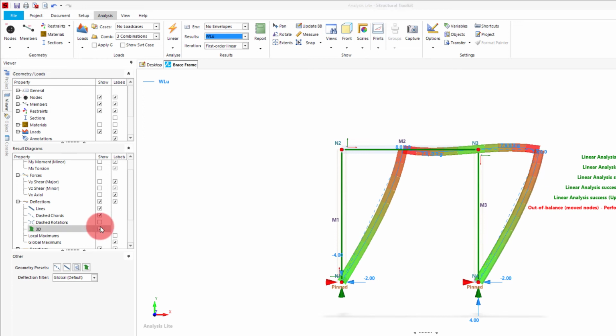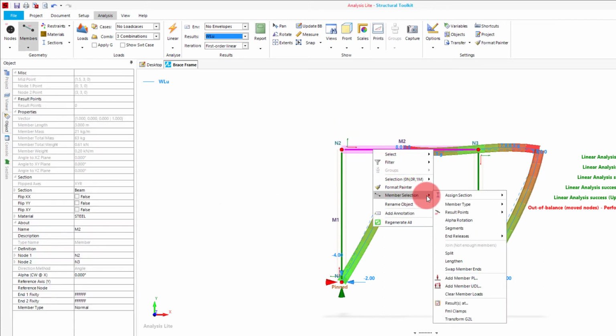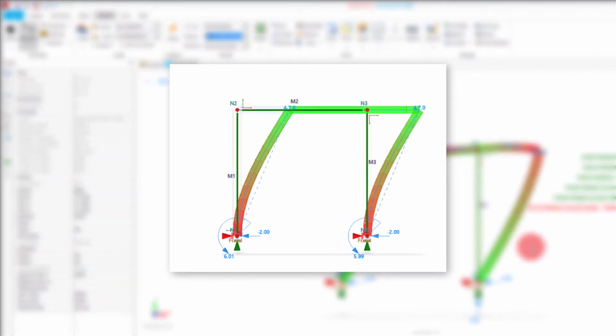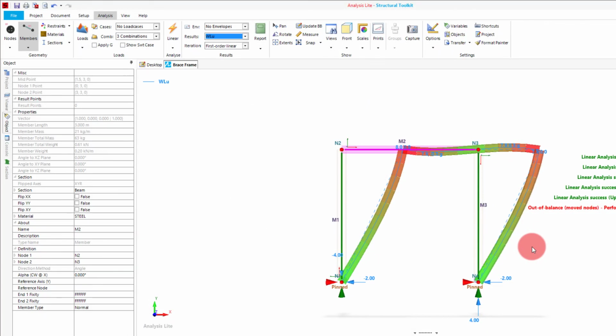If I were to change the beam ends to pinned, which can be done through using the fixity options we discussed before, or by using the end releases feature under the member selection and going to pinned, and also making the bottom restraints of the frame fixed, we would get an entirely different stress distribution, like we can see here on a different model. These options should give you a pretty good range of flexibility with setting up the kind of model you want.